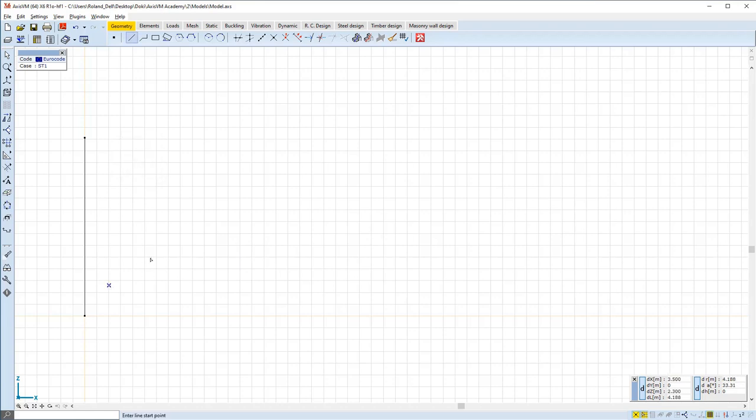So first I define a line quickly using relative coordinates for start and end points. Note that the 0, x, y, z coordinates means the insertion point itself. And then switching to global coordinate input, 0, x, y, z is the global origo.